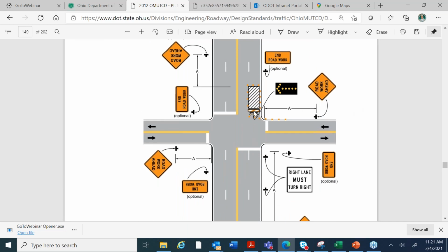As you can see in this picture, the work area is on the far side of the intersection in the right lane, just like we're going to be, but it's on up the street, right? But what we can do is we can set up the work zone just like this, but we would stretch this work zone with our cones or drums, either one, all the way up past where we're working. That way we don't have to worry about a taper and we don't have to worry about a buffer space because it's all taken care of with this design.